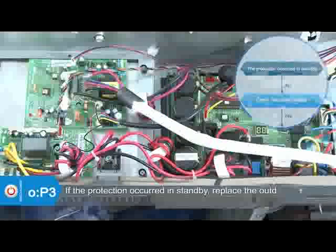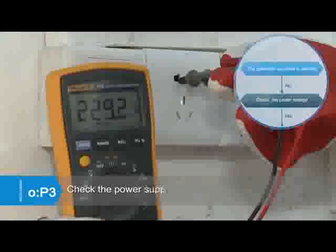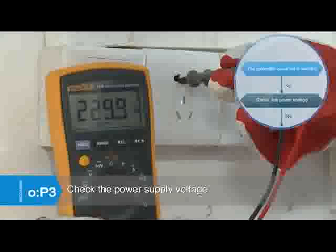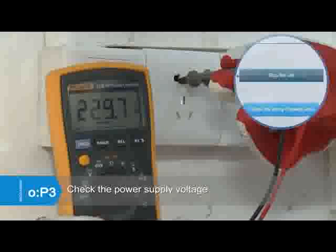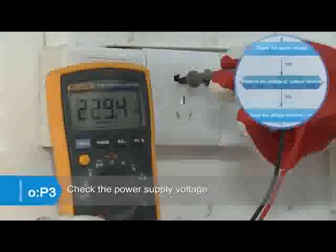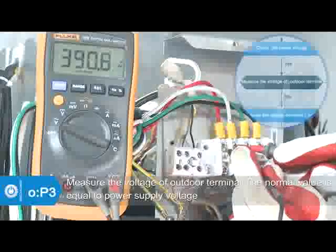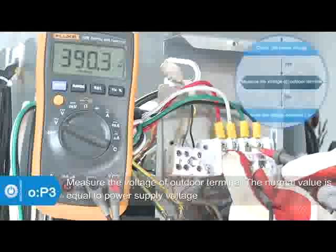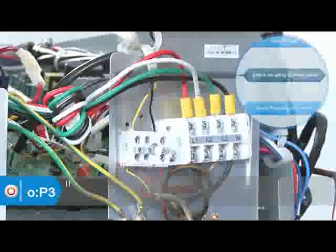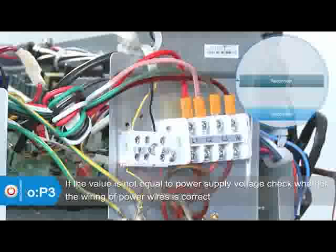If the protection occurs in standby mode, replace the outdoor main PCB. If the protection does not occur in standby mode, check whether the power voltage is normal. Restart the unit when the power supply is normal. Measure whether outdoor terminal voltage is normal. If the value is not equal to power supply voltage, check whether the wiring of power wires is correct.